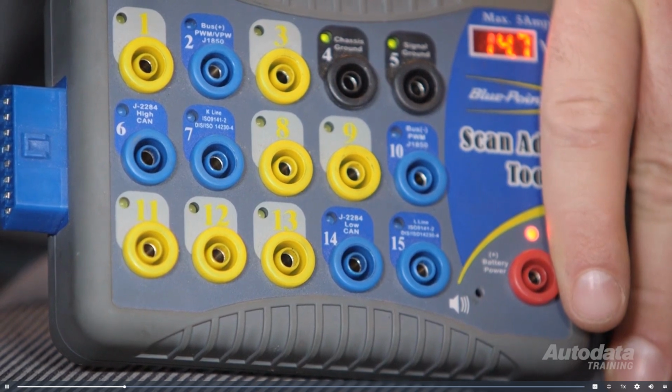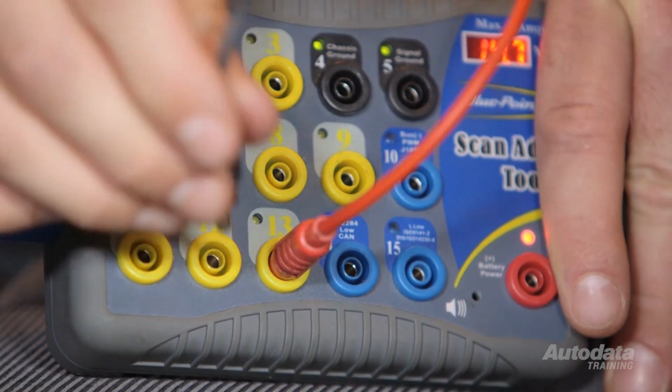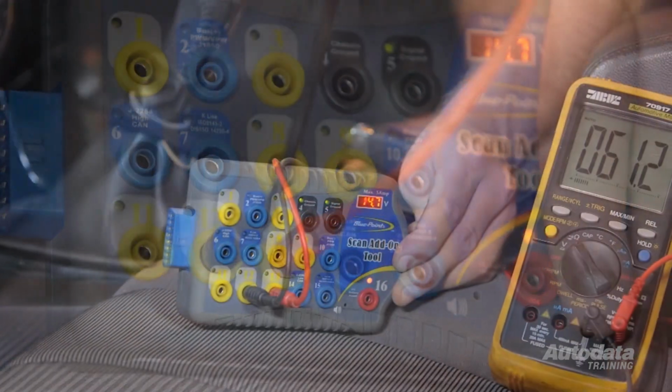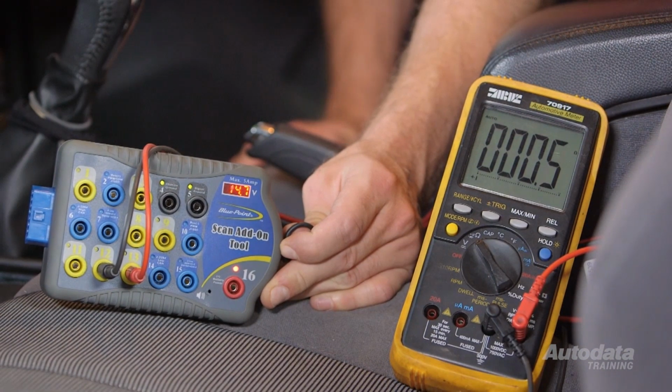Turn the ignition off and allow the bus to shut down. Connect a breakout box, set the meter to ohms and connect between the two terminals. 60 ohms should be seen in a correctly functioning network. If a substantially lower reading was displayed, this confirms the bus network has a short.